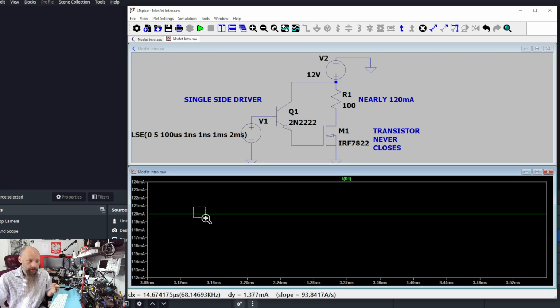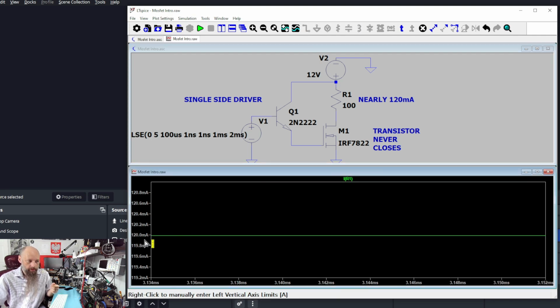And we can see that it's almost exactly 112 milliamps, which means our transistor not only opened completely, but it creates nearly no resistance in the circuit, just like a relay switch would, right? So MOSFETs are very much like very fast switches, and that's their primary use.